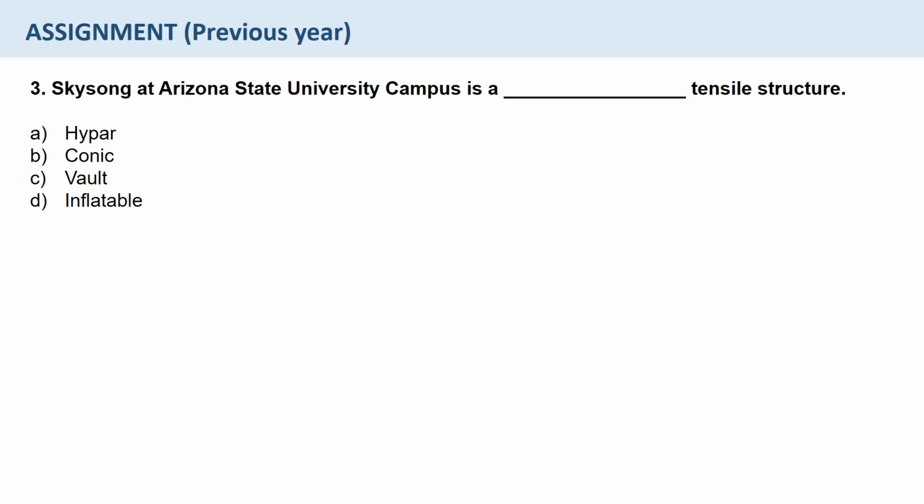What is a conical tension structure? It is highly effective for covering large areas. A conical tension structure is easily identified by its tent-like shape. Conical designs can feature either single or multiple masts. For both design options, membranes are tensioned between a ring at the pinnacle and the perimeter support columns. Cones are especially effective in areas that need to comply with high rain or snow load regulations.